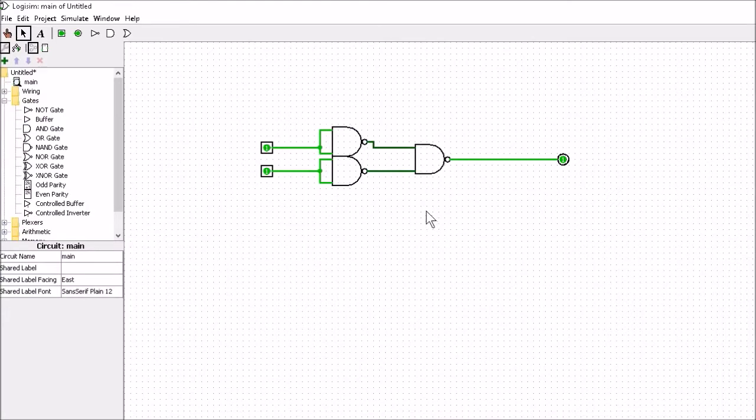So we can create an OR gate from 3 NAND gates, and that's the realization there. So we simply have a NAND gate, and these two NAND gates are connected together as inverters or NOT gates. So if we invert the inputs, we can create an OR gate. So this thing here is just the same as one of these.